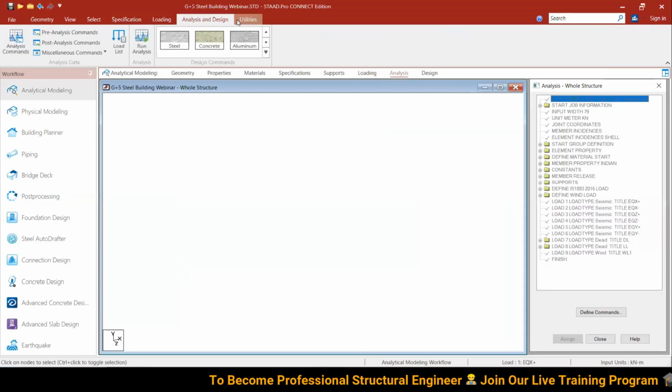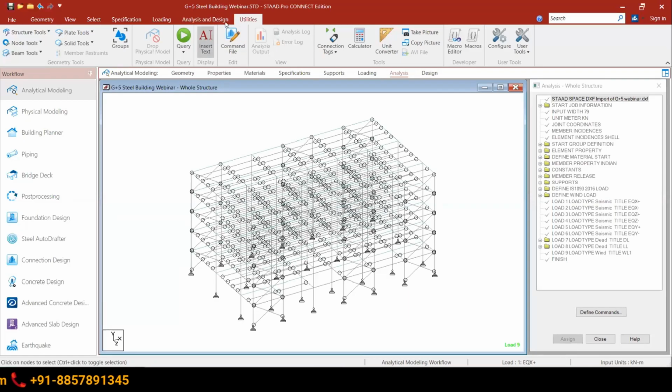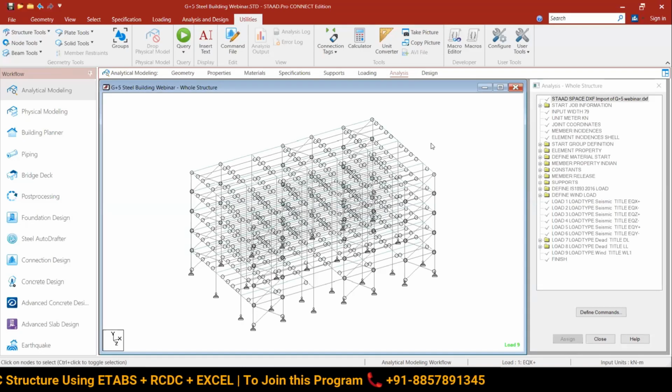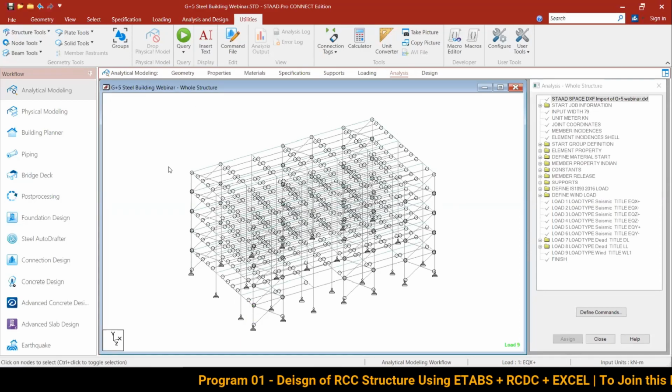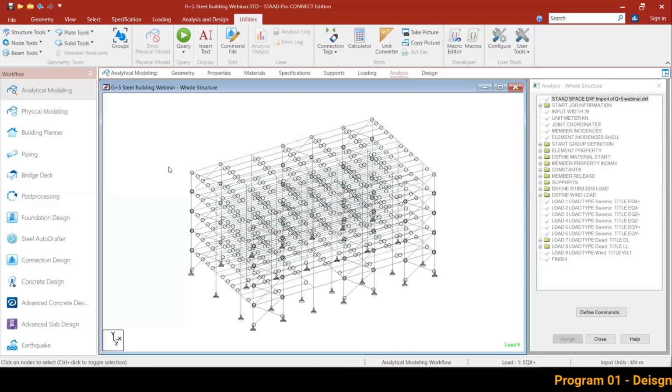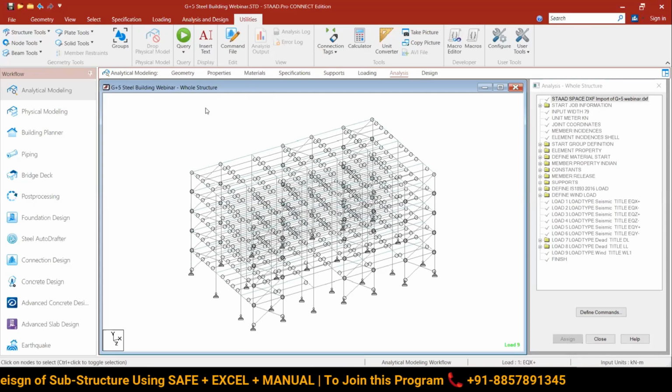Sir, you have given live load on the whole terrace, but there we need roof live load, because in earthquake we don't consider it. Okay, so on the terrace we don't have to give live load. Yes, because in earthquake we don't consider it. For earthquake we will define it; we haven't defined earthquake yet, we have defined the full general live load. When I am defining only live load, I will define it completely, as you are saying. It's regarding live load consideration for seismic, which we consider 25% if it is less than 3 kN per meter square. That is the next step, I will be showing you that. But at the terrace you are not considering live load. Zero.